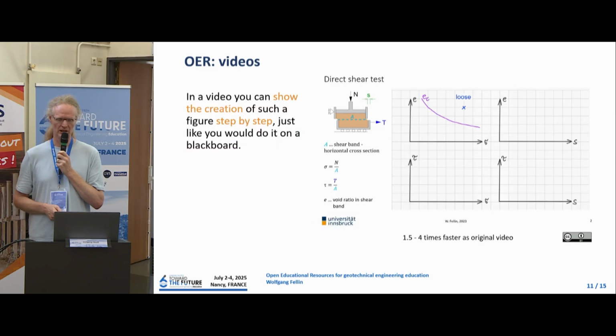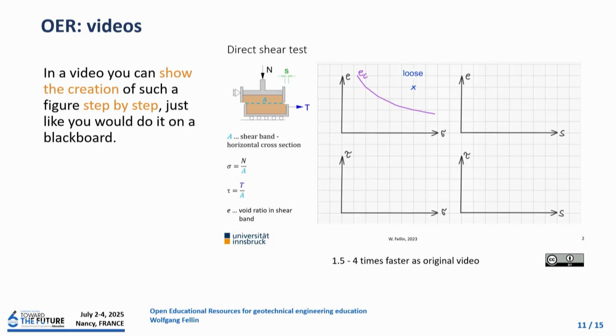The advantage of a video is that you can show the creation of such a figure step by step, just like you would do it on the blackboard. And you see here the evolution of the stress during the displacement, the evolution of the void ratio during displacement, the evolution of the void ratio during the critical void ratio. And you see here then the construction of the failure point in the normal stress shear stress diagram.